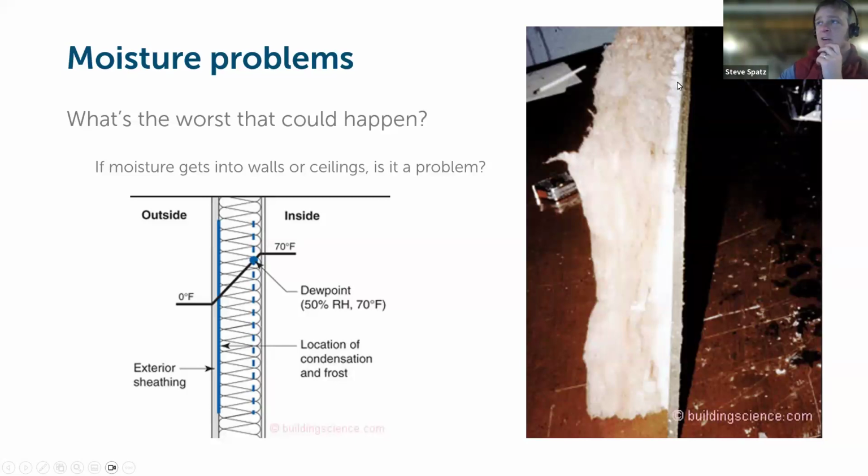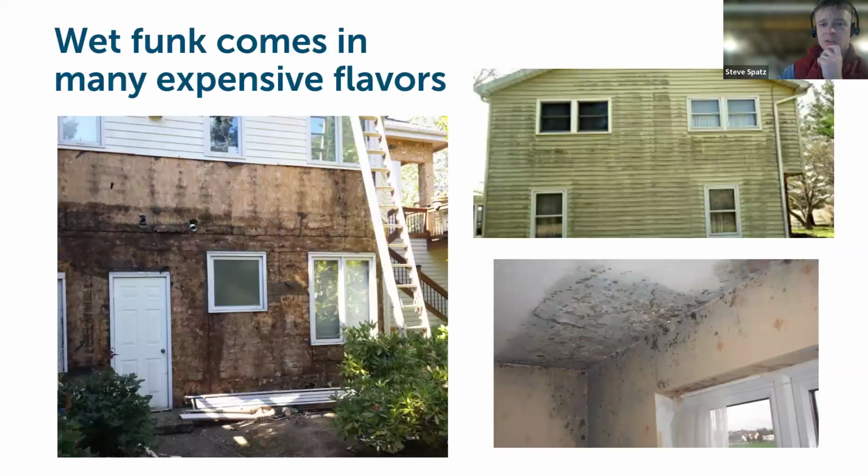This is actually a layer of frost, which is a cutout of a section of a wall assembly where this dynamic had been occurring. So this is interior vapor transport that has accumulated to that thickness of frost against the cold OSB in the middle of a heating season. So this is the physical dynamic of what can occur when we're not managing those control layers well. Here we go, back to those same examples again. This is the damage vectors that occur and what it can look like.